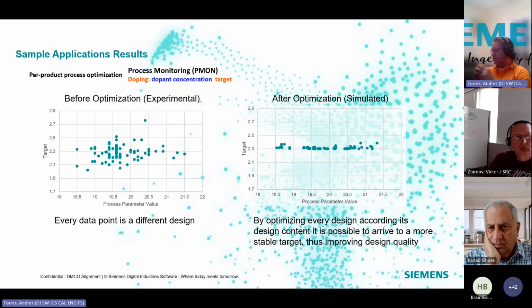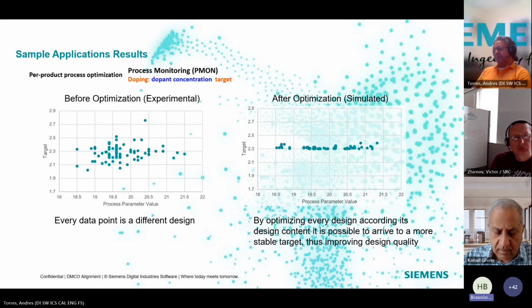A position across all of the lots. So what we have found is that once you integrate all of this data, there is actually a lot of information that turns out to be systematic, which typically has been considered to be stochastic. And we have been considering it to be stochastic because we didn't have a better way to do the characterization. But I have some slides that show that by combining everything, it turns out that there are more things that are systematic than what we thought there were.